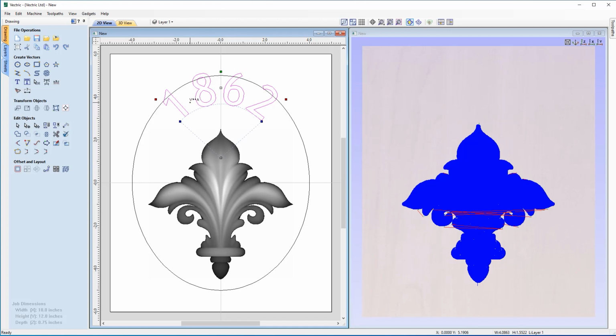Now you'll notice that if I hover my mouse pointer between each number, you have this little plus sign and two arrows pointing towards each other. If I just left click between them, you'll notice the numbers move closer together. If I do the same between the 8 and the 6 and the 6 and the 2, you can see they're slowly moving closer together. Similarly, if I hold the shift key down and click between numbers, so if I click between the 8 and the 6, if you pay close attention, you'll notice that when I click, they move further apart, and that's by holding shift while clicking between them. But I'm just going to edit the spacing so I get them a little bit closer together until I'm quite happy with it.